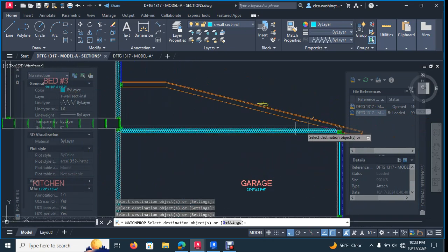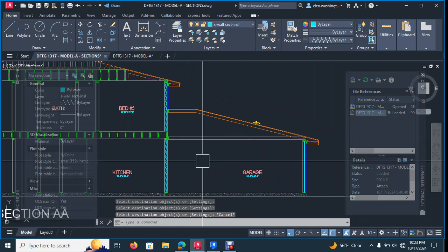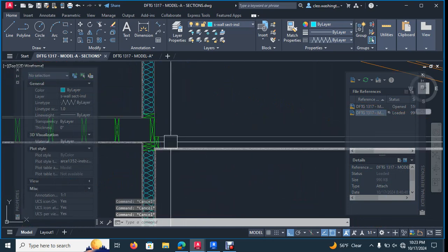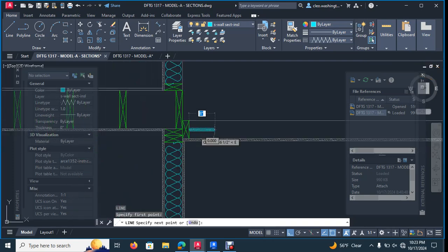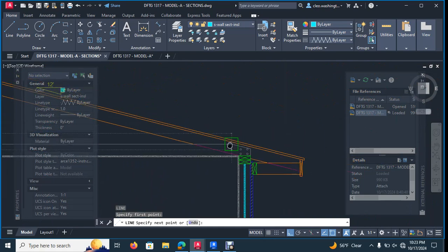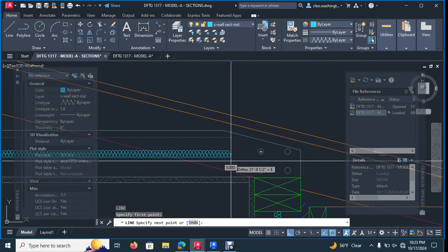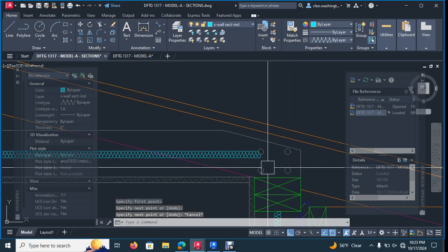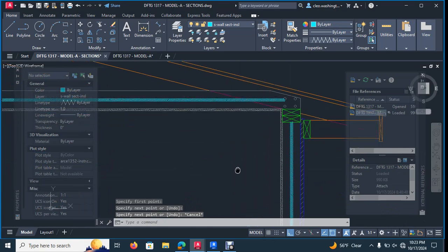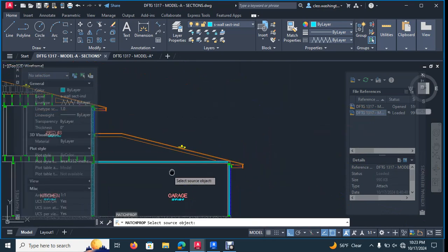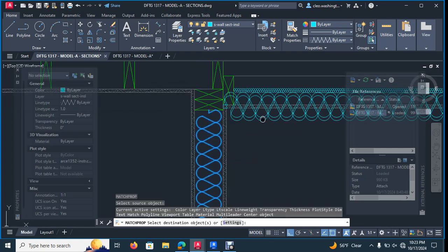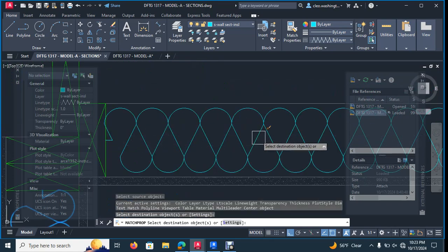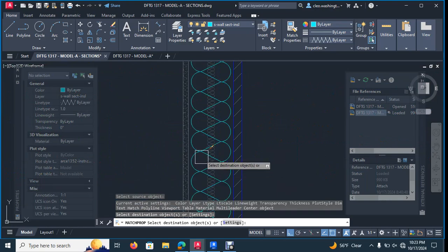Typically, you want to actually add some insulation in the attic. Yeah, I would. My house, I'm adding insulation, so hit L. Let's draw some insulation like this. Really, that's all you have to do. Just stop it right there. Now hit MA. Yeah, just like that. Then come make this one right.